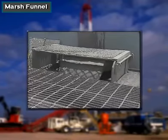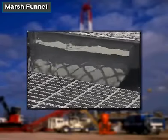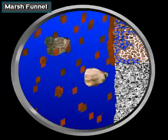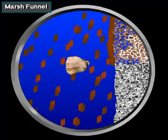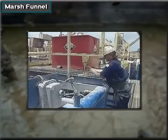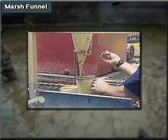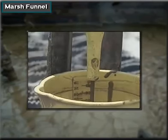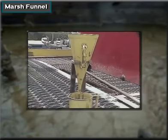The viscosity of the mud, its thickness or resistance to flow, is also an important factor. The mud's viscosity determines how well it can carry cuttings up the hole. One measure of a mud's viscosity is its funnel viscosity. That is, how many seconds does it take exactly 1 quart of mud to flow out of a special funnel called a marsh funnel.